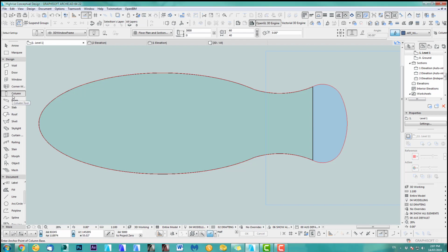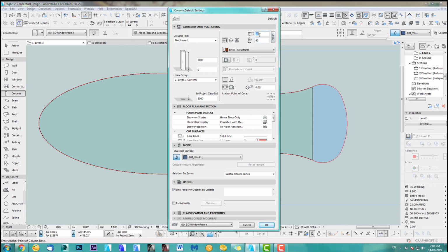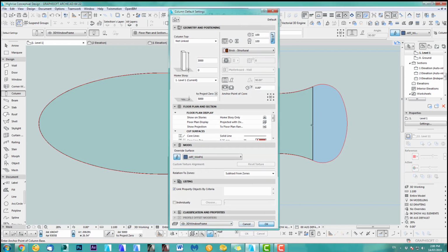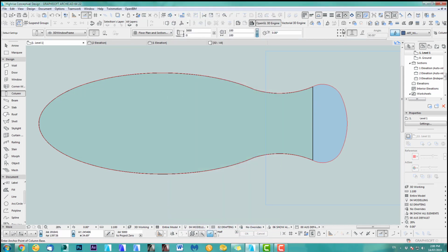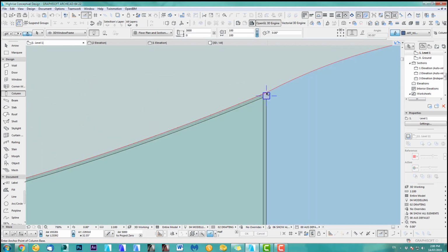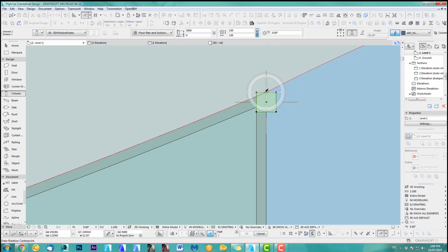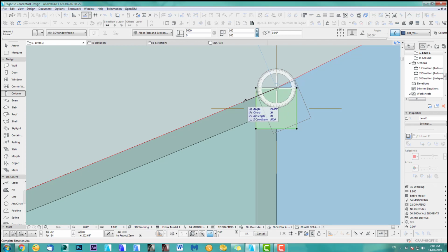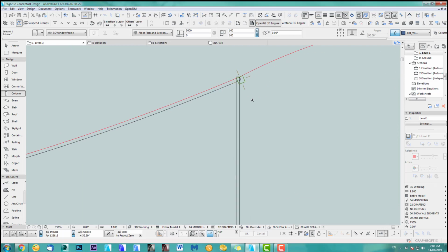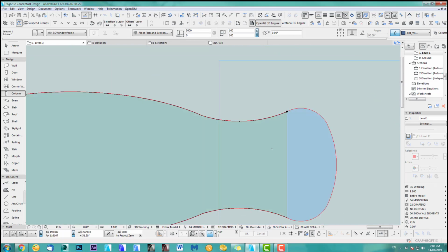So column, let's go to the column tool. I like to add a column, let's make them the same, 100 mil and 3, that's good. Window frame material, and I put them on 3D window frame layer. So add in the middle, or no, actually add it up here. There we go. So you zoom in, you click there, and you click again, because I wanted to move this so it's more perpendicular to our ellipse. Okay, great. So this is good, and now we sweep this along.